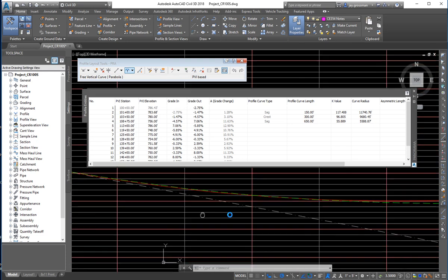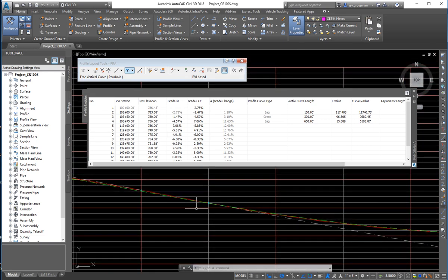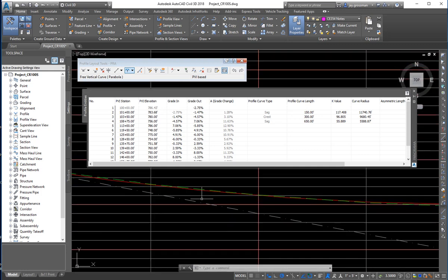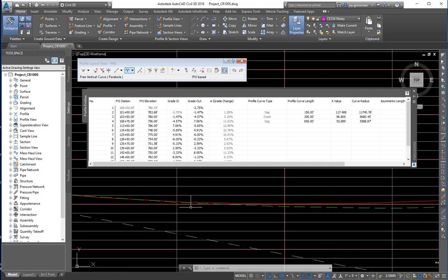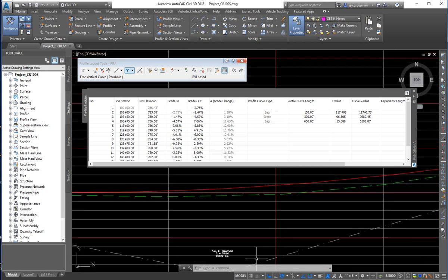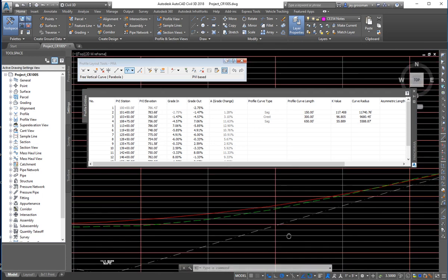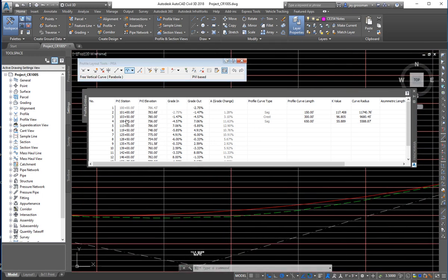So this is an iterative process. Get used to it. Now we do have 50 feet between tangents. We're doing really good on this side. I still think we're not far enough to the right. So let's go another 50 feet. Let's go 109. Let's try 109.